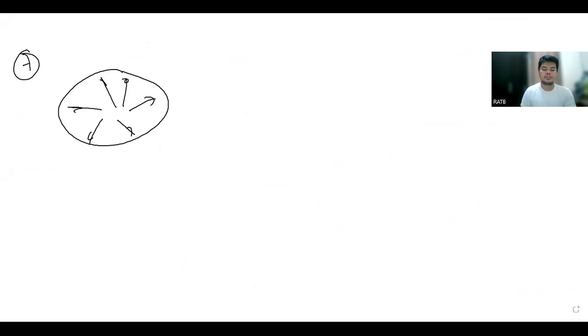So for the spherical tank, this is a very straightforward example. The internal pressure inside will cause a stress of 240 megapascal, denoted by variable P. So the stress is equal to the internal pressure multiplied by diameter D, that's 25 meters, over 4 times the thickness, given as 15 mm. So this is 15 mm.